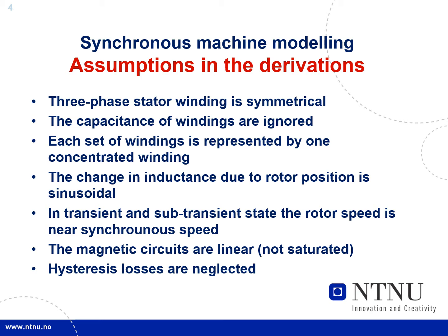We ignore the capacitances of the windings. We also say that each set of windings is represented by one concentrated winding. Of course, in reality, these are distributed somewhat in space. We also say that the change in inductance due to rotor position is sinusoidal, and we come back to that in more detail.